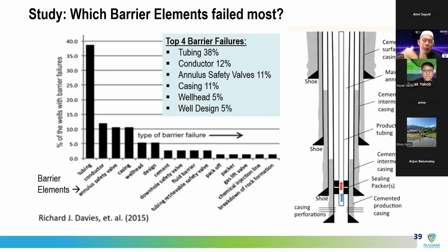So the tubing starts to really move up and down. And even when you flow, the flow is not always consistent. Sometimes high flow, low flow, so you start to vibrate. So tubing is much more exposed to vibration and stresses and so on. That's why you can see the failure of tubing is a lot.